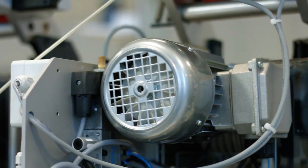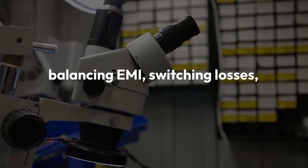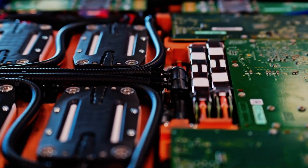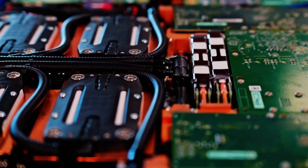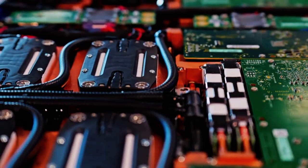In practice, many engineers start with a common value, then iterate and optimize based on actual circuit performance, balancing EMI, switching losses, and driver protection. Sometimes, different resistors are used for turn-on and turn-off by adding a diode in parallel with a portion of the gate resistor for asymmetric switching speed control.